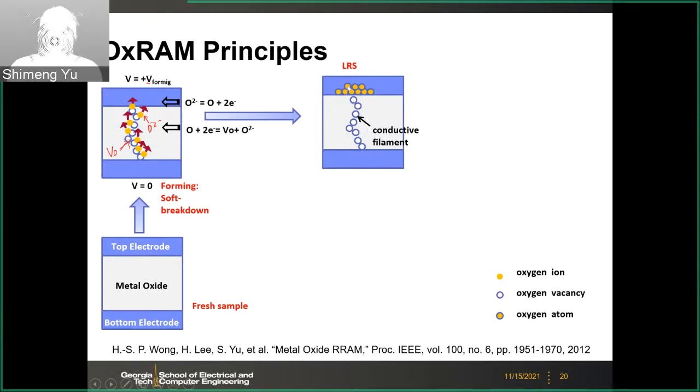And then the oxygen ions are deposited at the top electrode, and then they will be discharged and become like oxygen layer. It's not an oxygen layer. This will react with the top electrode or with this capping layer. For example, if the capping layer is hafnium, that means this interface will become partially oxidized to partial hafnium dioxide as an interface, because you get more oxygen here.